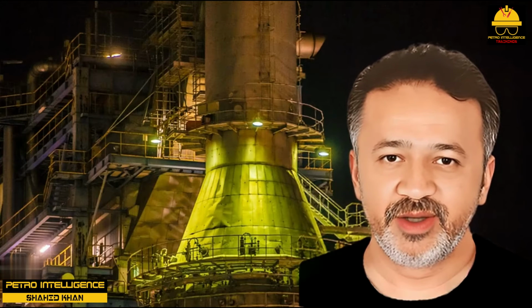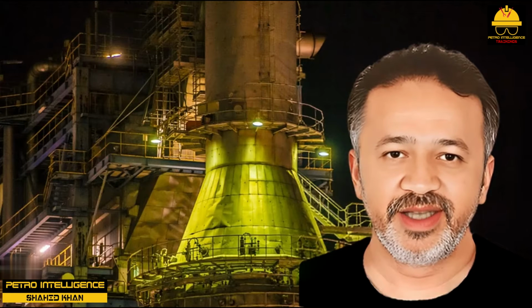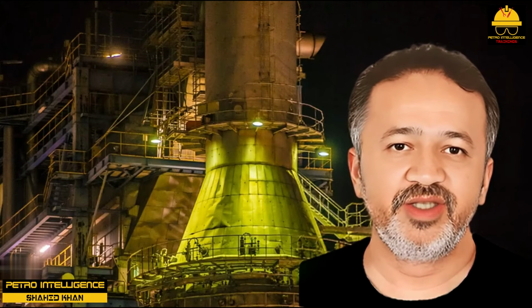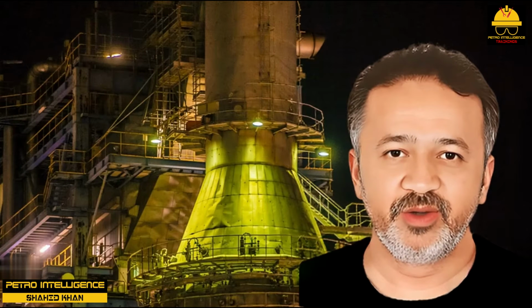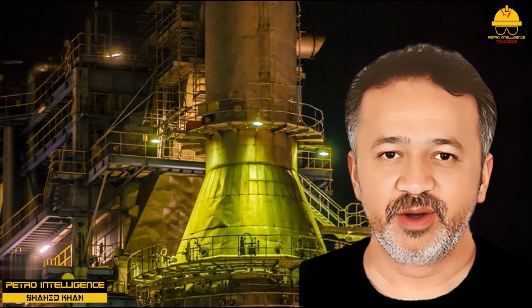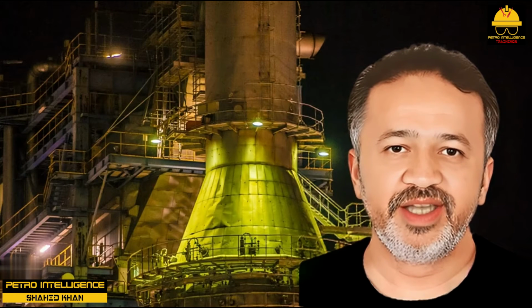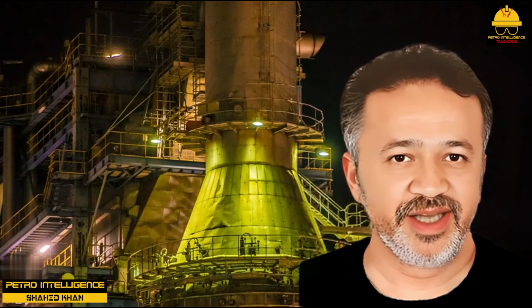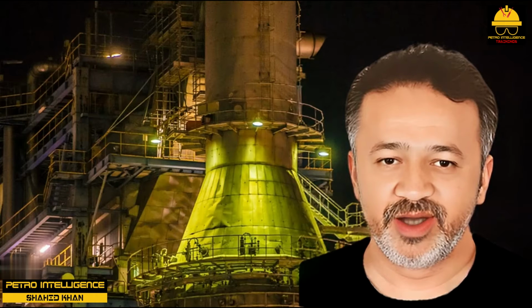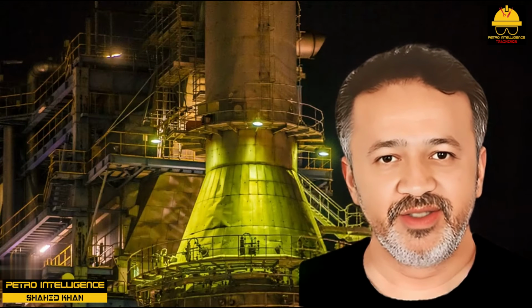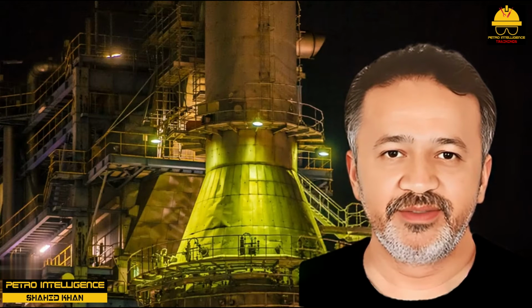The point of absolute combustion in terms of either maximum heater outlet temperature or minimum fuel fired for a given outlet temperature would correspond to the same flue gas oxygen content for a given furnace at the same moment in time. However, we must also note that this flue gas oxygen content that corresponded to the point of absolute combustion on, say, heater 3304A on Monday, January 2nd, 2023, at midday is not likely to correspond to the point of absolute combustion on the same heater on Tuesday, January 3rd, 2023, at midday, or even Tuesday, January 2nd, 1996, 1 hour or 1 minute after it was first determined.